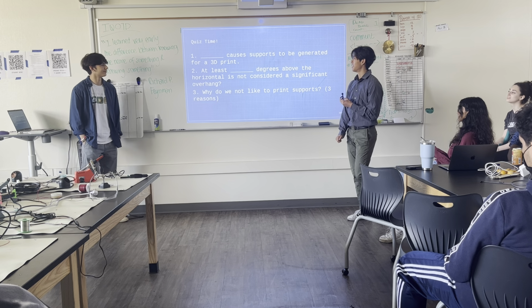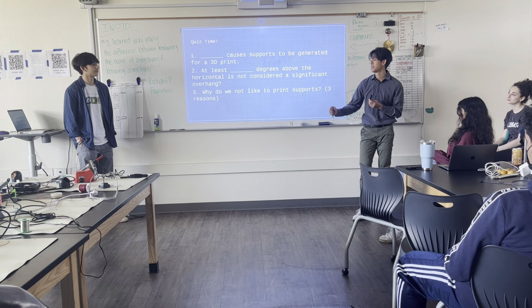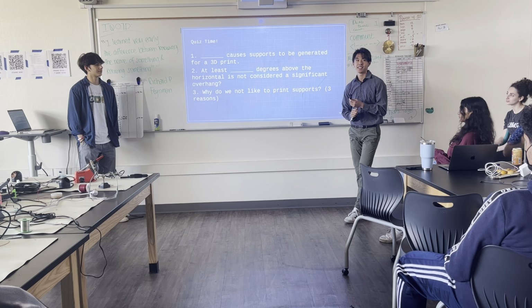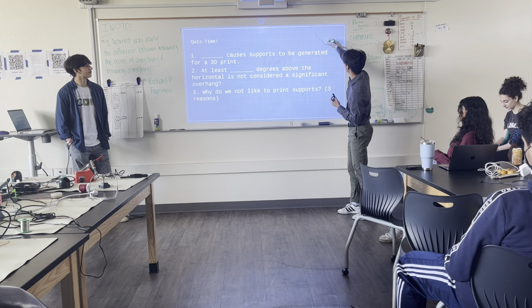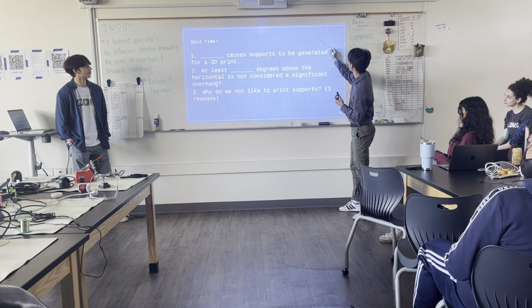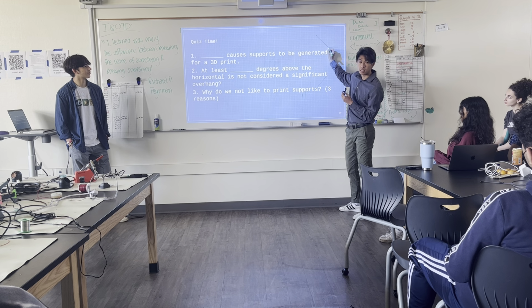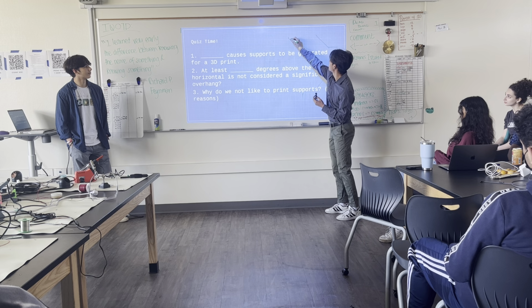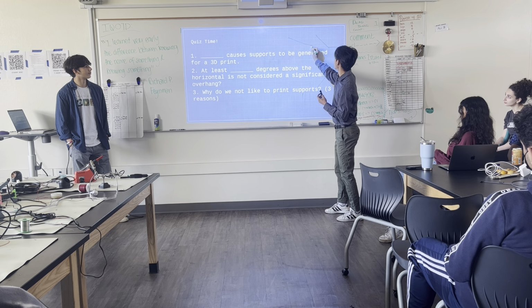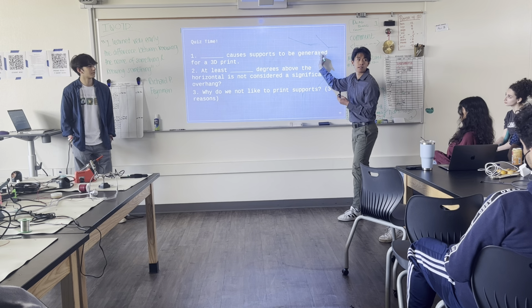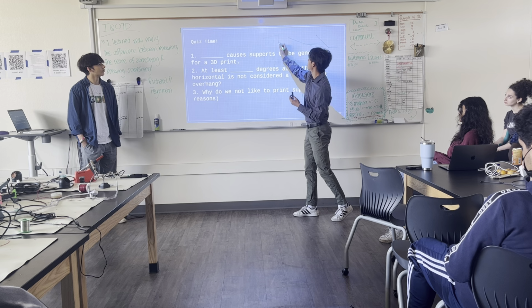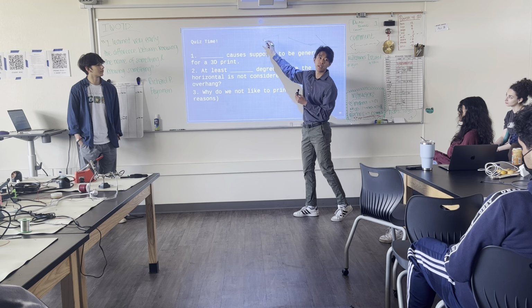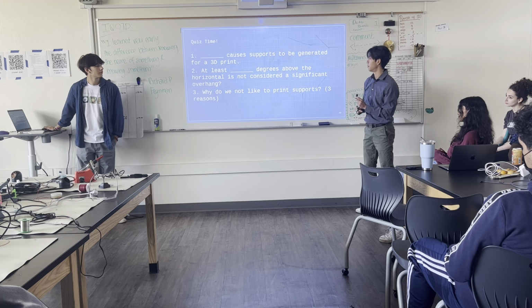Yes, that's right. Overhangs. And how many degrees? I didn't really say this explicitly, but it was on the slides. Yeah, 45. The reason for this is that each layer can kind of support itself with the previous layer. But if it's anything more, the layer is too far away to be supported by the previous layer. Does that make sense? If you're at a 90-degree angle, then you really are just printing in midair.